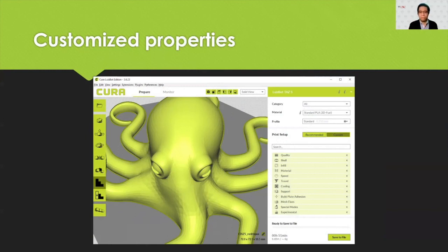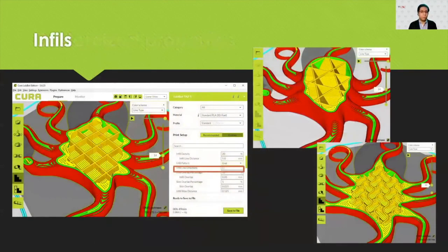practice makes perfect. One more thing that we can customize is the infills. In the video, we saw that we can change how much material we will be using to fill the inside of our piece, and that the more we use, the stronger it will be. However, this will also increase the weight of the object, the amount of material required, and the time to complete the print.